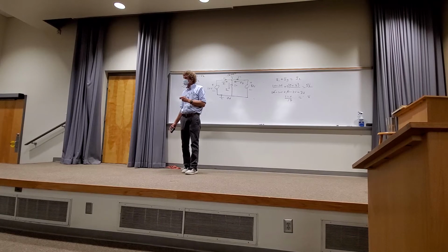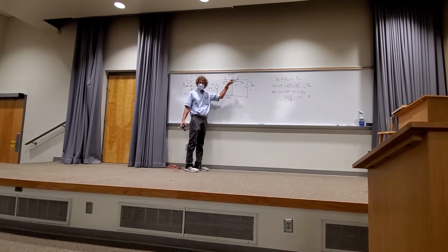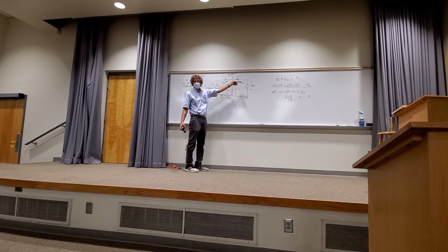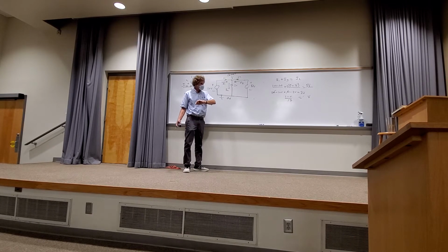The way you do this is first, if you have a junction or a node with an unknown voltage, you assign current directions. Now the way I always do it is I always go from left to right on the top part and from top to bottom. Now this is an exception because there's a voltage source there, but you can just as well go that way, all right? And then you would have I1 equal I2 plus I3, right? But the value of the voltages will be the same. And that's very simple.